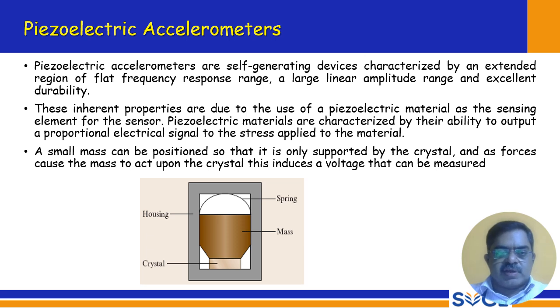Piezoelectric accelerometers are self-generating devices characterized by an extended region of flat frequency response range, a large linear amplitude range, and excellent durability. These inherent properties are due to the use of piezoelectric material as the sensing element for the sensor.